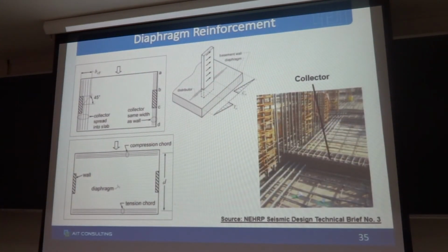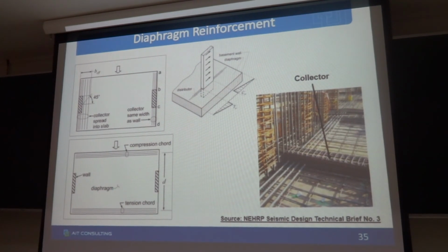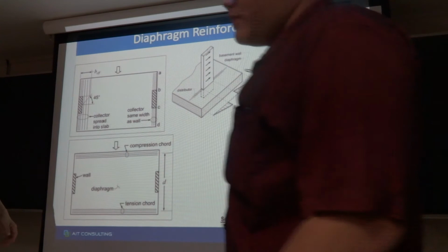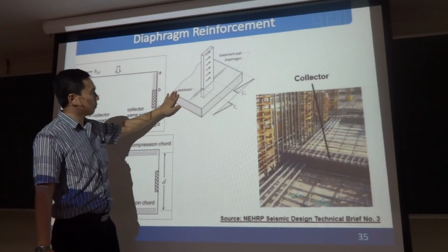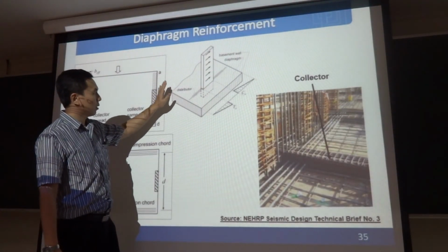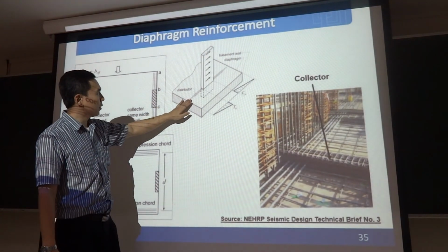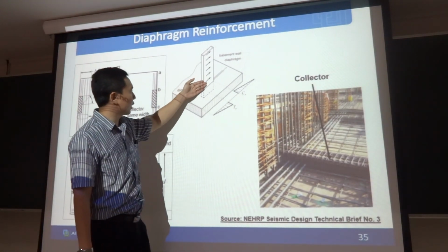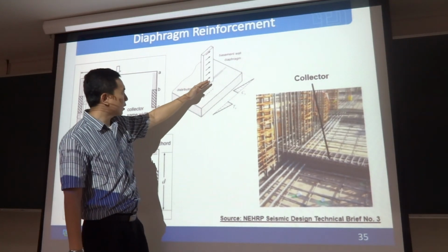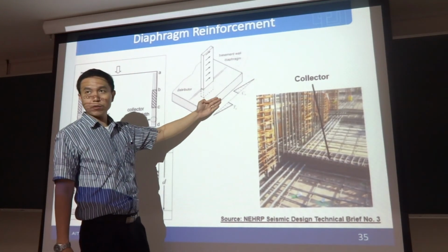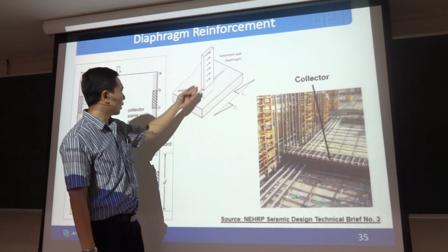So this is for diaphragm design. For the diaphragm design, we have to check axial forces, shear forces, and the flexure design. Here, this is the ground level diaphragm, and the shear force coming from the shear wall will be transferred through this diaphragm to the retaining walls.